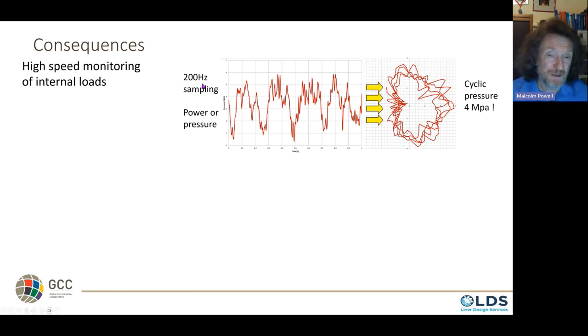So you don't see this in a control room. Control room, the best you see is 1 hertz. So all of that would become one average signal. This is 1 second, 200 hertz, 5 oscillations per second of the crusher. So they're 5 peaks.